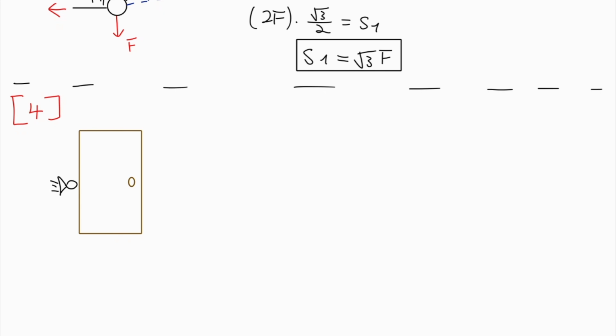So a very simple real-world example to prove this is to use a door, okay? So imagine if you're trying to push a door. And if you push somewhere like here, very close to the hinges, you're going to have to push with a lot of force in order to move the door, right? This is compared to if you push all the way at the very end or close to where the doorknob is, then you can use a lot less force to push the door open. This is simply due to the moment that you generate.